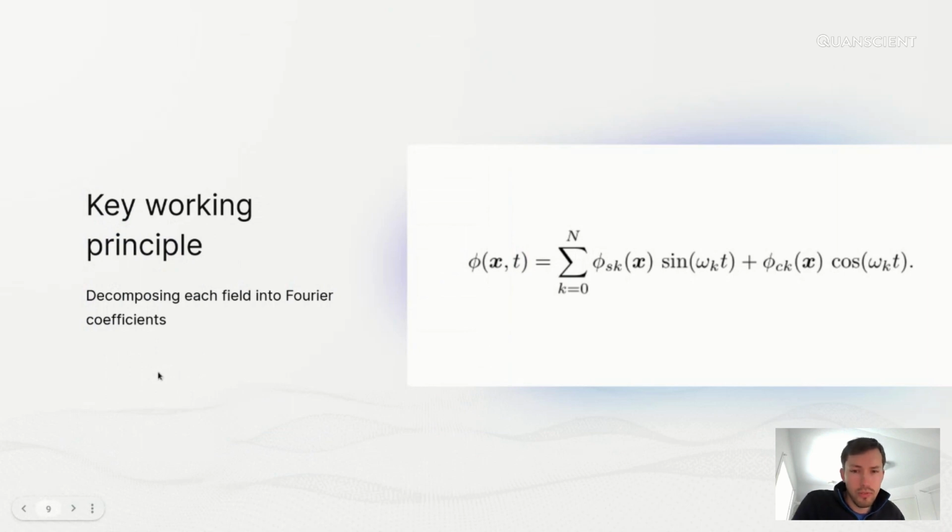Now you have a multiplier to this fundamental frequency because you have a nonlinear problem. When you drive with, let's say, 1 kilohertz, you might have 2 kilohertz, 3 or 10 kilohertz harmonics appearing because the system is nonlinear. You might also have DC components appearing, even though you drive things purely in an AC way. So if you set omega to 0, then the first term, the sine, is always 0. That's not of any use. The cosine of 0 is 1. And this actually shows the appearance of this phi C0, which we call harmonic 1. So harmonic 1 is the solution that's going to give you the constant component of your problem.